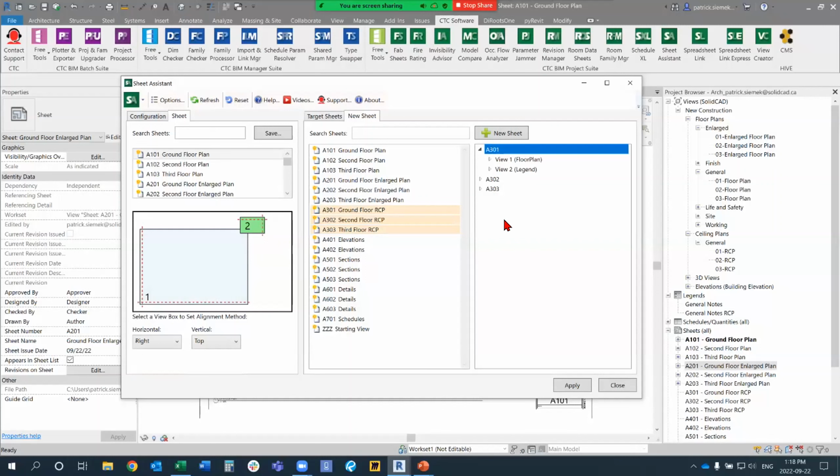So view 1, which is that overall floor plan view, as I expand, we can now select what view I want to be placed directly onto that sheet. We could skip to not place any kind of floor plan on that sheet. I could always duplicate an existing view and have it duplicate with a detailing, give it a view template and even a naming suffix. So again, you could quickly create new views directly from this tool also.